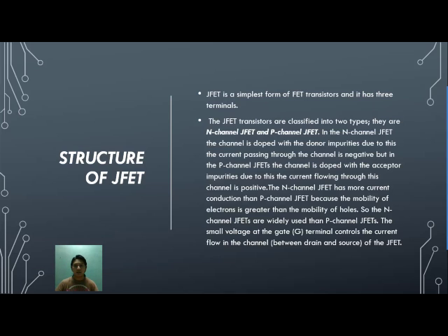The N-channel JFET has more current in conduction than the P-channel JFET because the mobility of electrons is greater than the mobility of holes. So N-channel JFETs are more widely used than P-channel JFETs. The small voltage at the gate, G, terminal controls the current flow in the channel between drain and source of the JFET.